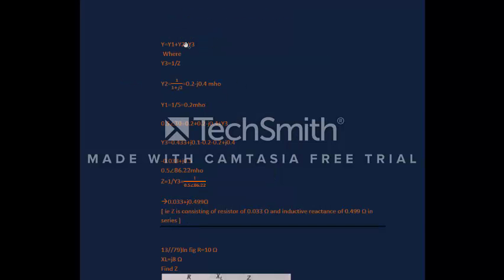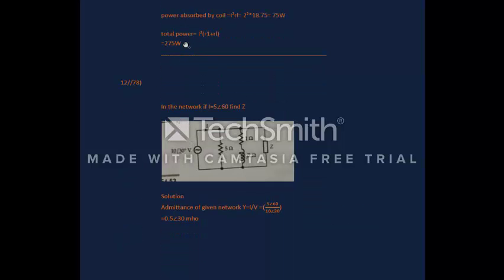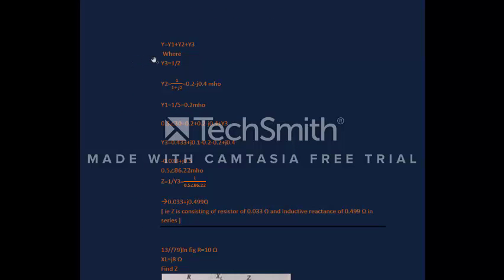Y1, the admittance, as we see, the admittances add up. Y is equal to Y1 plus Y2 plus Y3. It is simple to add these values. Where Y2 is equal to 1 upon 1 plus j2, which turns out to be 0.2 minus 0.4j mho. Y1 is equal to 1 upon 5, which is equal to 0.2 mho. 0.4∠30° is equal to 0.2 plus 0.2 minus 0.4j plus Y3.